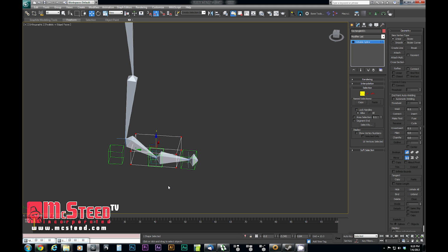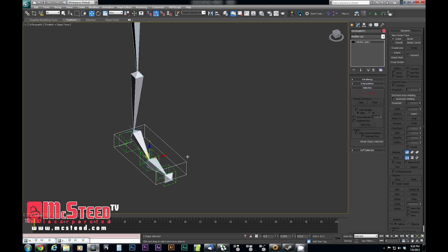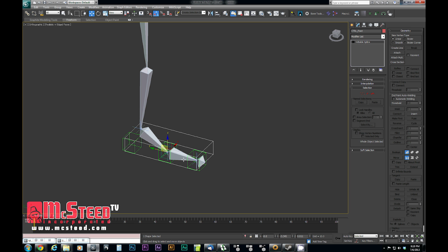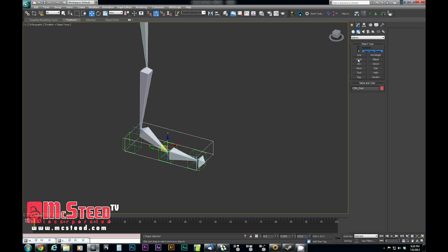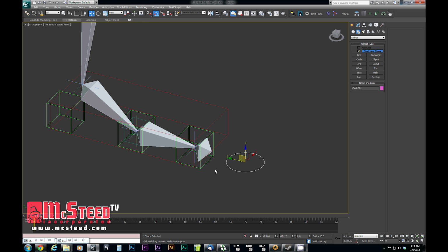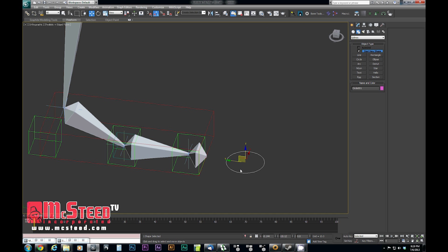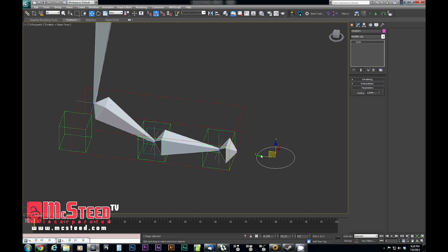So I'm going to shape this to be around the size of where the foot mesh would be. And this is going to become my main foot control. So I'm going to call it control, or CTRL underscore foot. And now I'm going to create a control for the foot roll. And this is one of the big things that I do that I think is different than a lot of people. I don't like having lots of things that I have to go over to the modify panel to control. I like to have things that I can just click on in viewport and move around.